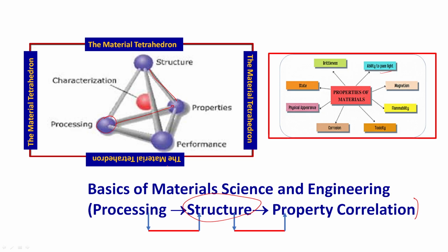And another important aspect of copper is it can be made into different shapes, because copper, as you know, has FCC crystal structure. So, therefore, it has many slip systems. It can be easily deformed into different kinds of shapes, wire, rods, whatever you want. So, these all together gave copper the advantage, and that is why you cannot have a cable in the world made up of anything else other than copper. We cannot even think about it.